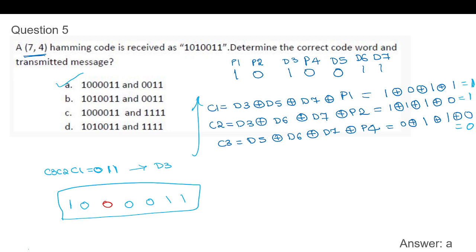So next we will go to XS3 codes. XS3 is an unweighted code. To the BCD number, say binary coded decimal, we add 0011 to get XS3.